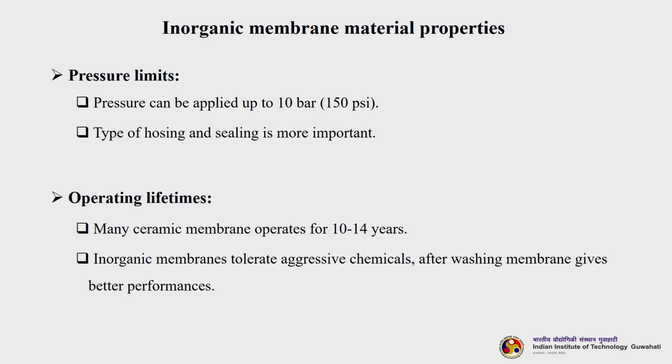Obviously any membrane, whether polymeric or inorganic ceramic membrane, we need to wash because of concentration polarization, fouling, both external fouling and internal fouling. So, we need to wash it. Once you wash, the performance of membranes actually increases. Washing is very easy in case of ceramic membrane, that is the message. In polymeric membrane, the washing has to be done very carefully or in a controlled manner, whereas for ceramic membranes it is easy.